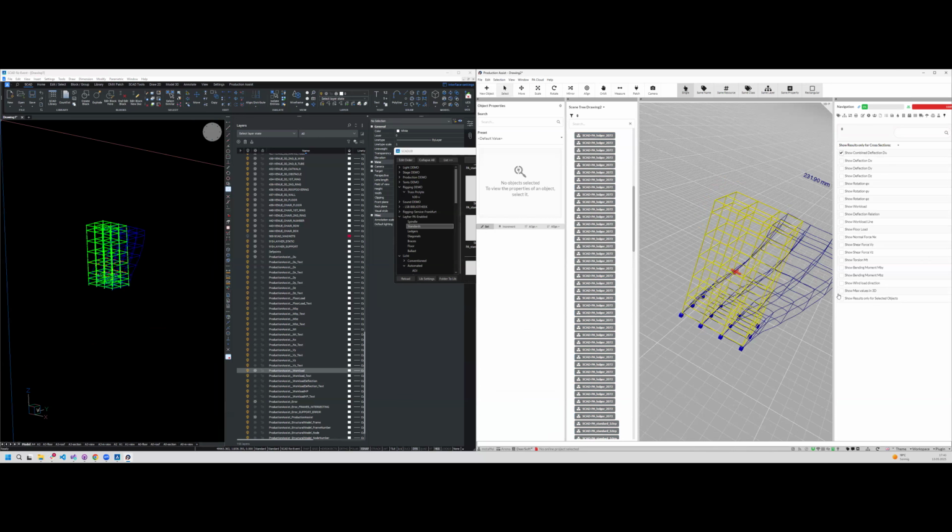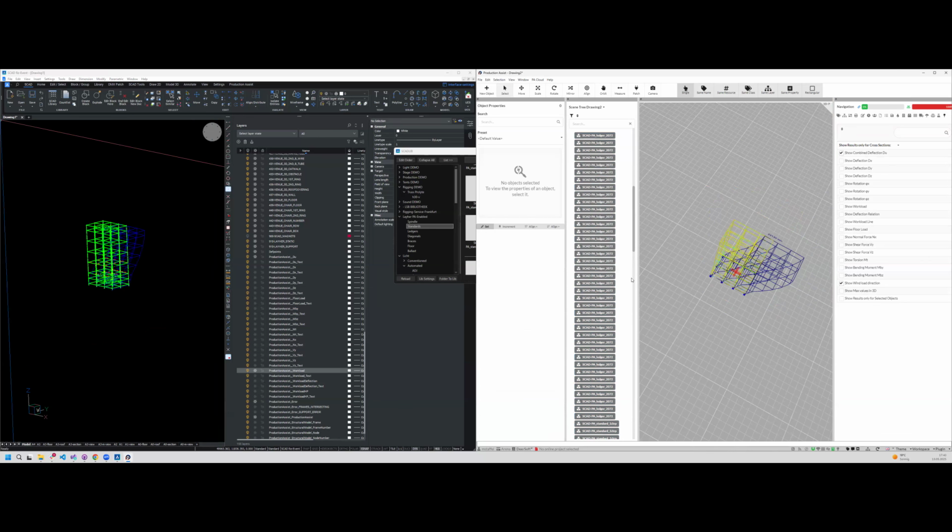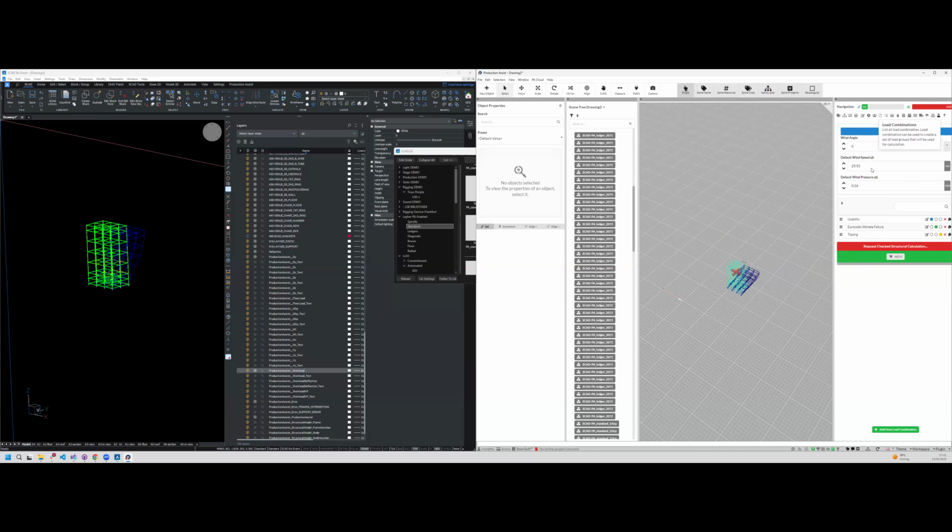When you click on the wind load direction, it will show you that the wind is coming from the X direction. You also can change this. If you go to the load combinations in here and change it maybe to 10 degrees, then you will see it sweeps out with this. And then we do 25 with this. Every time you change this, it will calculate the wind load and the deflection. Just for simplicity, we will leave it like this so that it's going to the side and it is not covered, but only the ledgers in here.